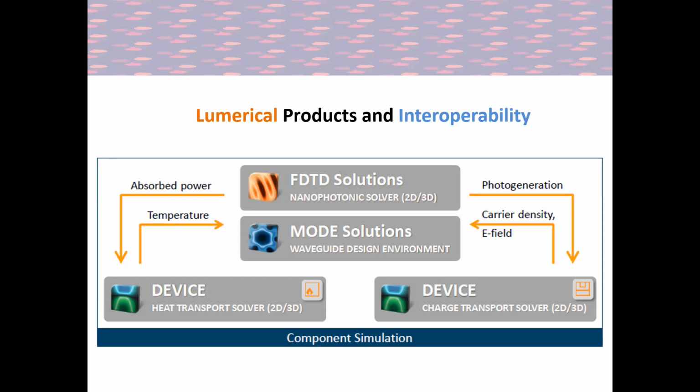For example, what is an example of the heat transport? If we create a modulator like a Mach-Zehnder interferometer, and we need to modulate or manipulate the light, we can manipulate it using temperature to change the mode or the characteristic of the light on one side.